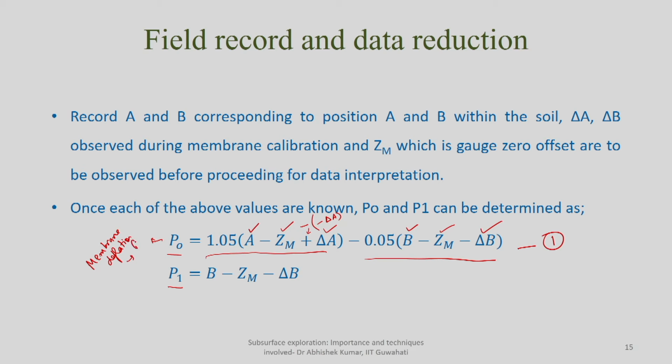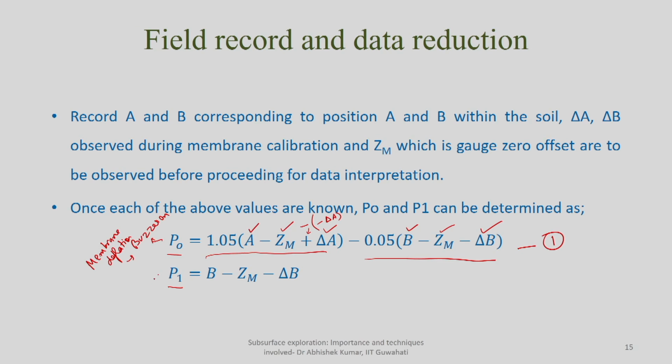That will be indicated by the buzzer sound, buzzer on, because initially, if you remember, the insulating disc came in contact with the membrane, and that's how the circuit was complete. This corresponds to 1.1 mm membrane center movement.